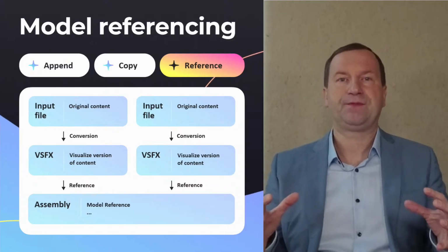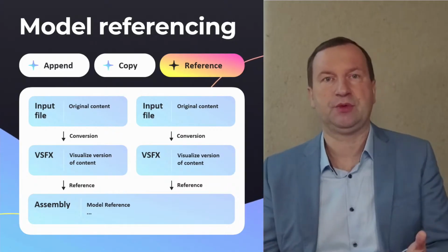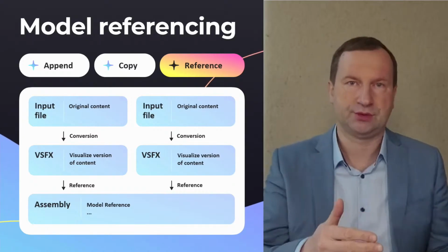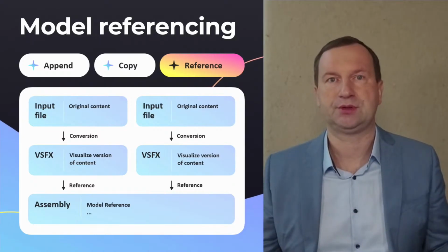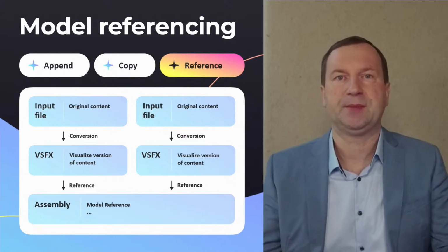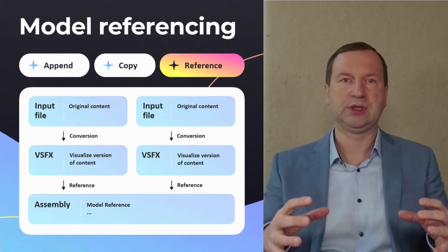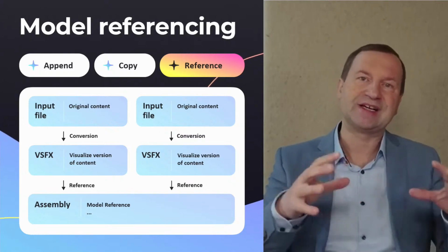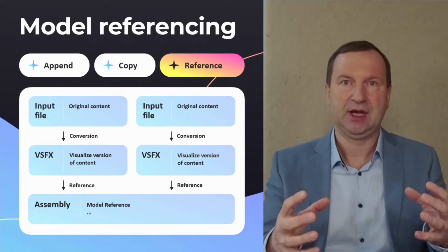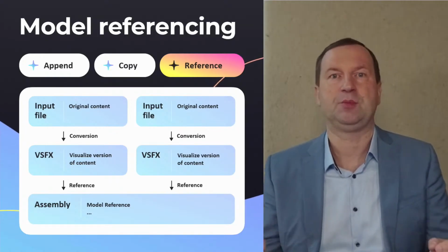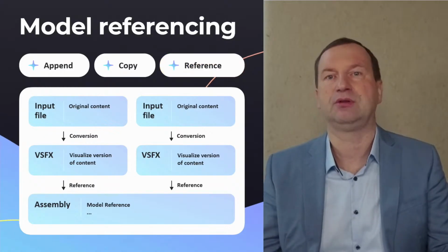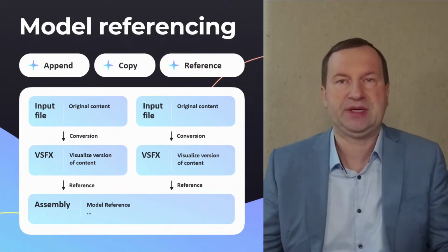If the input VSFX file supports partial viewing mode, model reference will also support it without additional configuration. A single Visualize database can combine both models and model references in the same scene. So model reference does not impose any restriction on other database content.